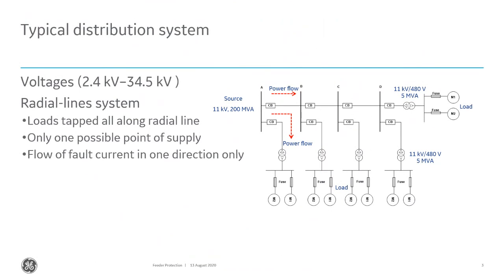So just schematically how everything operates. Obviously, there are multiple distribution lines that go to multiple locations, to multiple load pockets. So every distribution line will leave the substation via a breaker. So you have a circuit breaker at the substation. Then as it gets out into the distribution world, you might have overhead reclosers, and we'll talk about the purpose of reclosers later on. Or as it goes even further, you might have fuses.